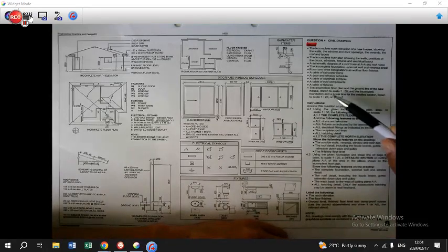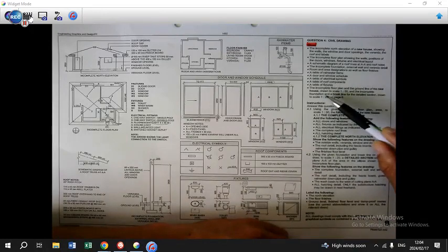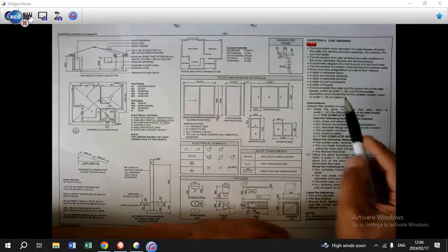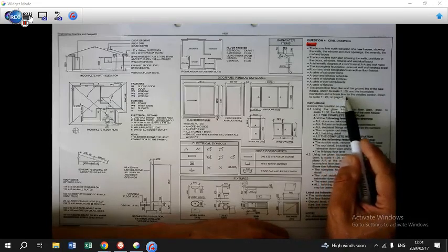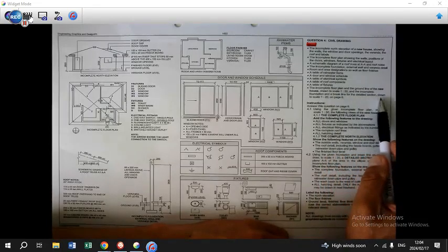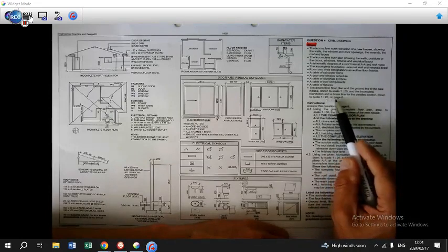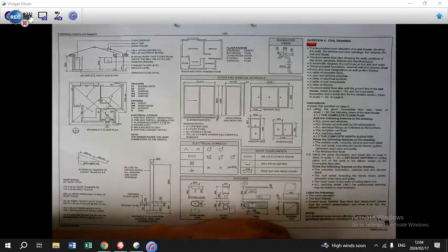Keep in mind that the incomplete floor plan and the ground line of the new house drawn to a scale of 1:50, and the incomplete foundation and a break line for the detail section drawn to scale 1:20 will appear on page 6, and that is the page which you are going to set up and draw.